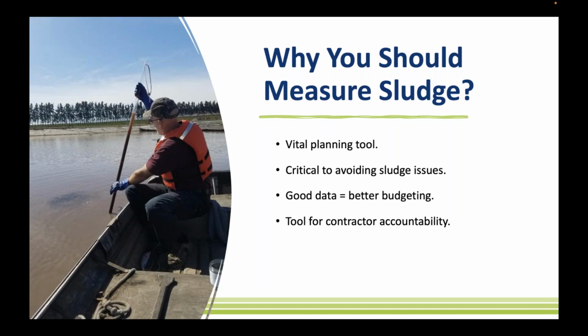Well, I think first and foremost, it's a very vital planning tool. You don't want to be in the position where you are having a fire drill come spring because you had a turnover event that is really acute due to all the sludge you have in your lagoon. So if you understand how much sludge you've got in the lagoon, and you can see how quickly that sludge is building up year to year, then you can plan ahead. You can project forward. You can say in 5 years we need to remove sludge. We're going to be at that 2-foot mark, right? Where that's going to be a little bit too much sludge. So it's really critical that you plan in order to avoid the issues associated with sludge.